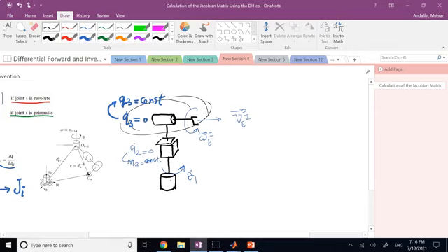So if I say, okay, what is omega? Well, you say omega is the same as theta 1 dot, except theta 1 dot is just the magnitude. It also needs a direction. And I ask you, what's the axis for joint 1, for theta 1 dot? And you say the actuation axis for joint 1, we call it Z i minus 1, which in this case is Z0. So I can write it as theta 1 dot times Z0. Of course, Z0 in I.